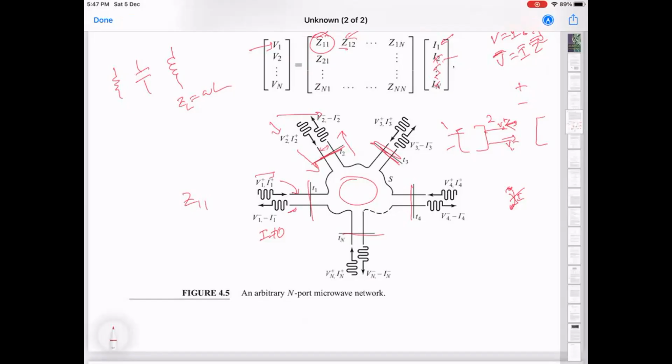I don't think that's what they meant to do. It's not that this is some incoming line and this is an outgoing line, but the two together are representing the two terminals of that port. It's just that in the drawing, the incident and the outgoing wave have been drawn next to each other. A transmission line always has two terminals, right? So these two wires here are representing those two terminals, not two separate wires, one for going in and one for going out.